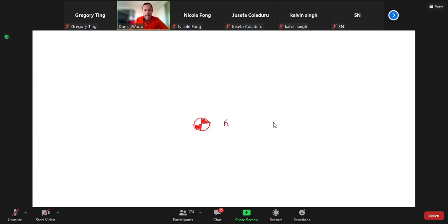Okay, so I've got a body. That body has mass, M, and it's acted on by gravity, which is 9.81 meters per second squared, and that acts straight down, vertically down. I'm just using this as a reference frame. Typically I have an X axis and a positive Y axis, and this is how I usually define my axes whenever I'm drawing a free body. There we go. This is my first free body diagram that I'm showing for you.